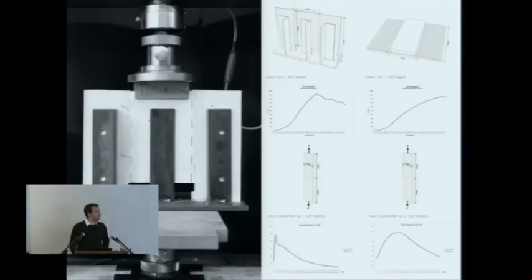It's also clear that in order to do so, you really have to understand a little bit the structural behavior of these finger joints. That's also not so difficult because you can imagine that these joints are quite good in transferring shear stresses along the edges. If you want to move this thing here, it actually is quite stable, but they're also very weak in transferring bending moments or even tensile stresses. I can hardly take this. So if you consider that it's only a viable joint for transferring shear, that constitutes quite a considerable challenge for the design of a larger blade structure.